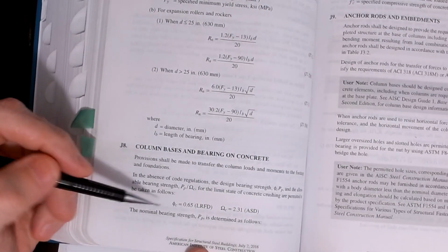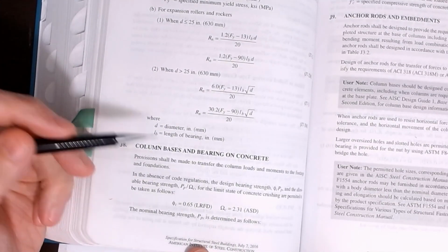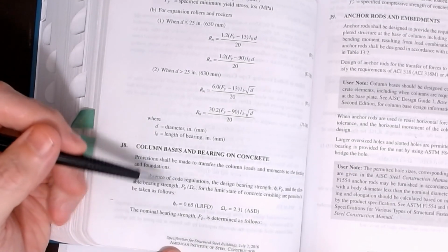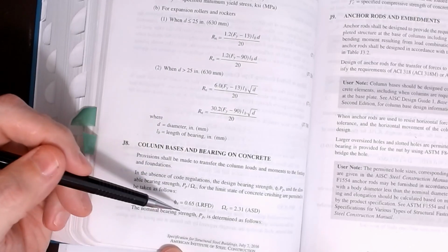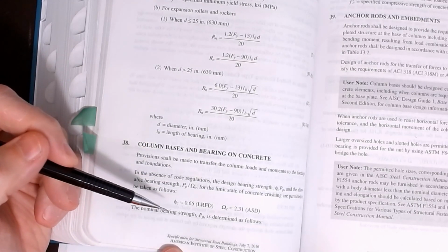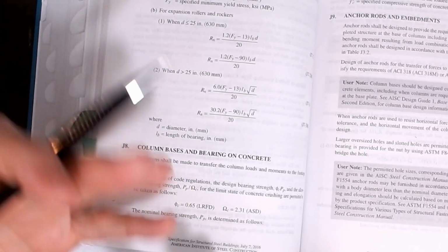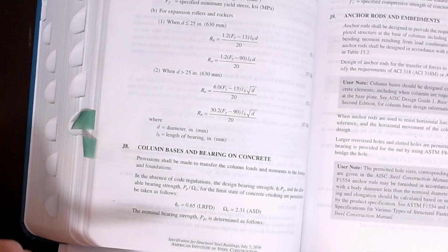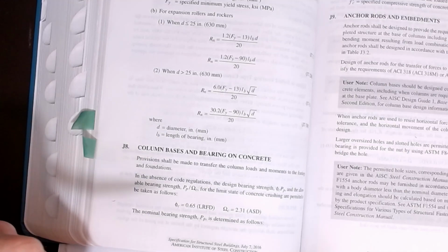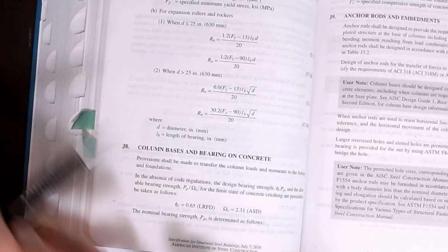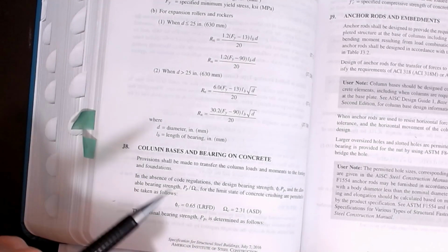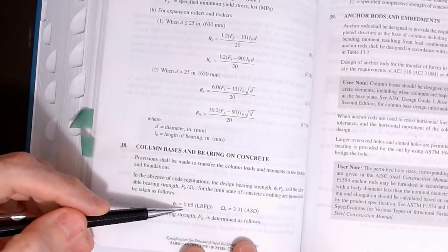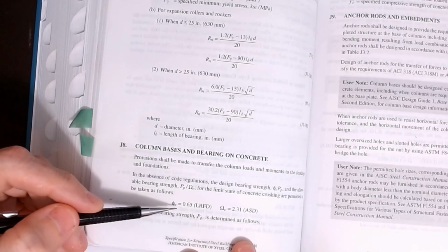Now you can see that phi for this is going to be 0.65. It's one of the lowest phi values that you'll see. And part of that has to do with the fact that you're bearing on concrete, and where we were using phi of 0.9 when steel yielded because it was a very ductile failure. When concrete fails, generally it's a very destructive and very dangerous situation when cracks and things can form in concrete. And once you crack concrete, you cannot uncrack it. Okay, so that's why this value is really, really low for our phi value.